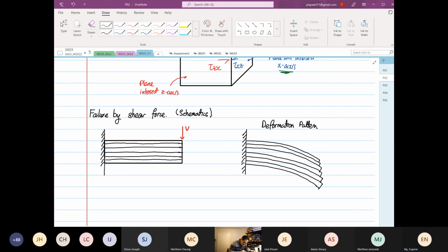If you look at where V is applied, the shear stress is in this direction. So if I draw my transformation, this is X, this is Y, this is rotation in our Z. That is how the shear stress due to V will initially react.